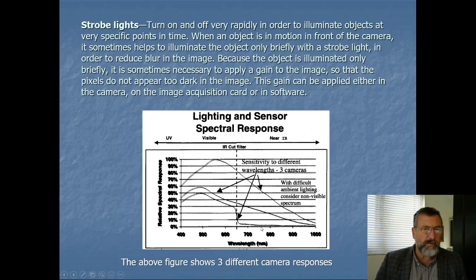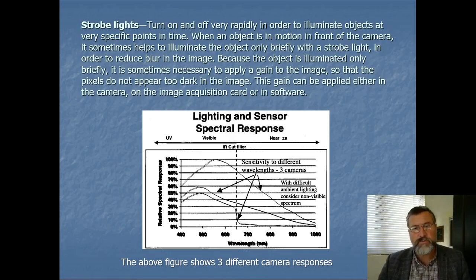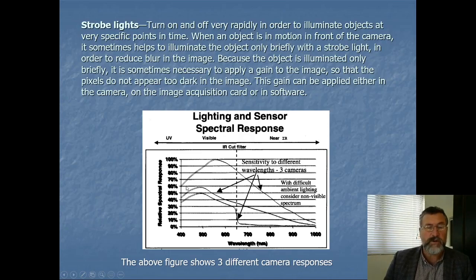Now, this can sometimes be a problem because, one time we were doing a project for a company in the States. We were using laser triangulation to measure objects that were going to be air freight on aircraft. And we were using deep red, so we were using wavelengths about here. But the cameras we were using had this nuisance thing built into them called an IR cutoff filter. These were Sony cameras, but they felt obliged to put this IR cut. So this is an infrared cutoff filter. And the idea of it is that it simulates the way the human eye works by cutting out wavelengths you can't see, because humans obviously can't see infrared.